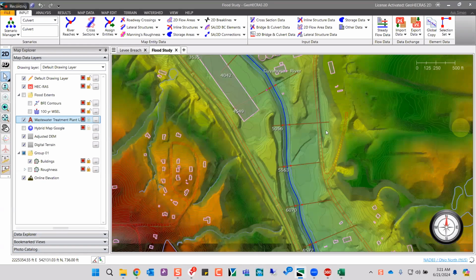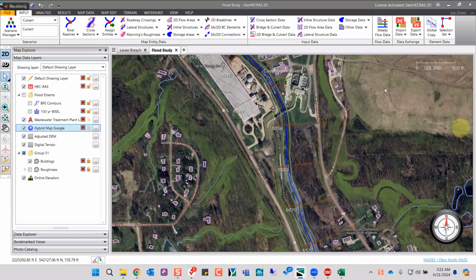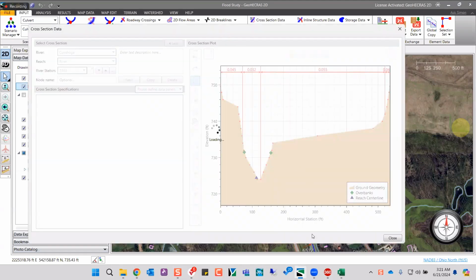You can see these points which you have here, these are all the intersection points with your contours. So you have limited points here. Now, if I were to extract this geometry using a DEM, go to extract geometry. This time I'll use elevation grid and use the DEM.